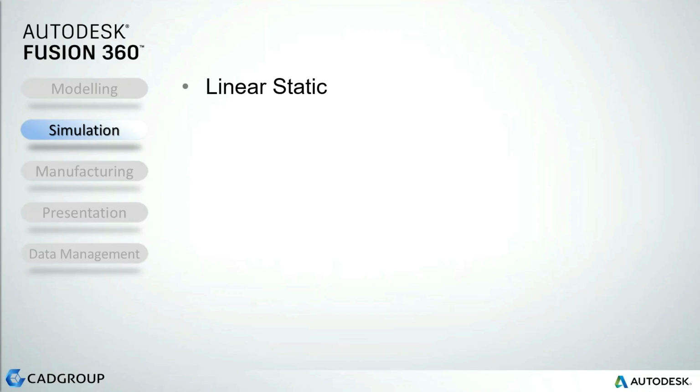In Fusion 360, you can do a variety of simulation studies to analyze your design under different load and constraint and even material combinations. There are several different studies available. You can have linear static analysis to calculate displacements, stresses, and reaction forces due to applied loads. You also have modal analysis to find the natural frequencies of your components. You have buckling analysis, where you can analyze for loss of stability of components like frame members.